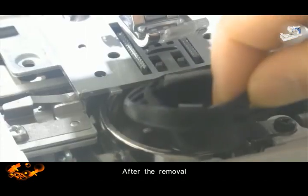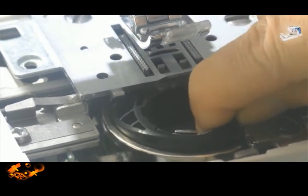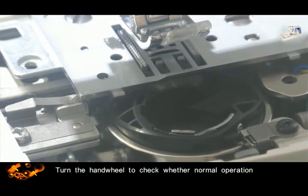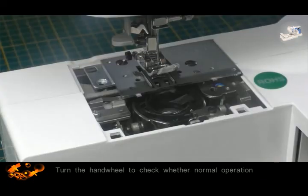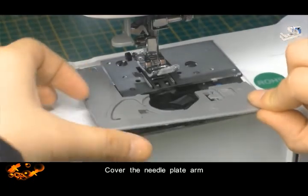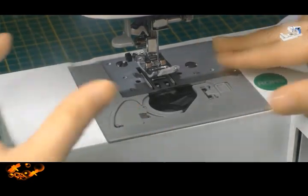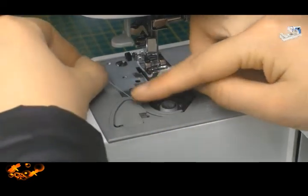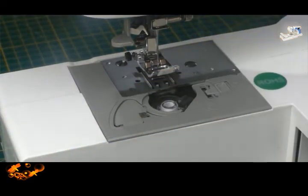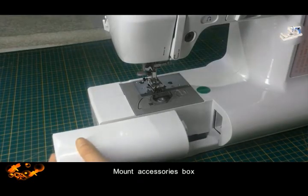After cleaning, load the hook normally into the bobbin case. Turn the hand wheel to check whether it operates normally. Cover the needle plate arm. Add the bobbin. Put on the transparent bobbin cover. Mount the accessory box.